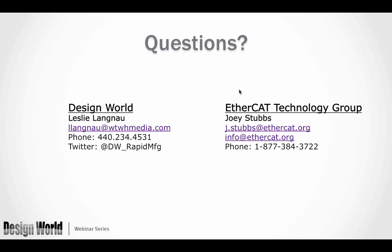Okay, can you describe the service channel a bit more? Yeah, it goes beyond this particular presentation on distributed clocks, but the service channel is the way we handle asynchronous communication. So either configuring of inputs and outputs on a device or moving standard Ethernet frames through EtherCAT. So if we want to service a Modbus TCP device or a web browser on a device, then we can use any leftover bandwidth to tunnel those protocols inside the cyclic EtherCAT frames.